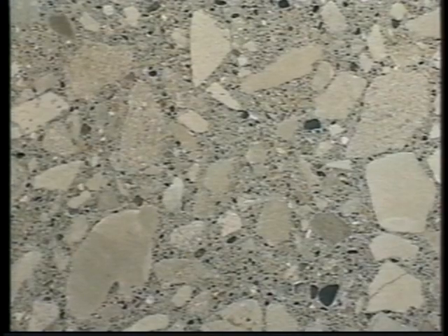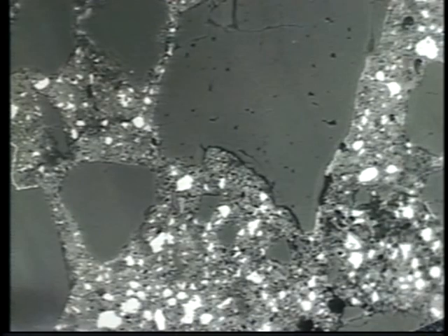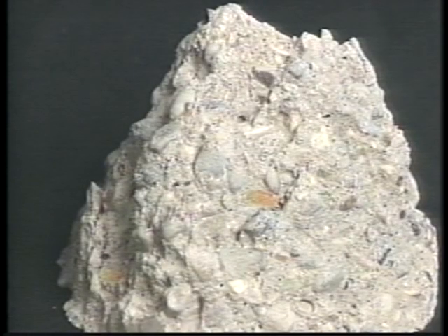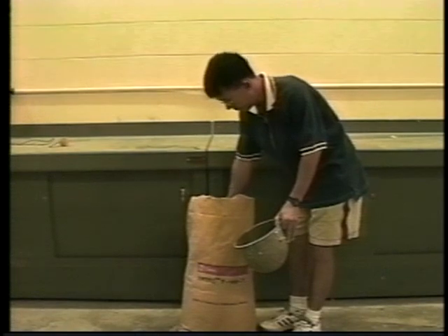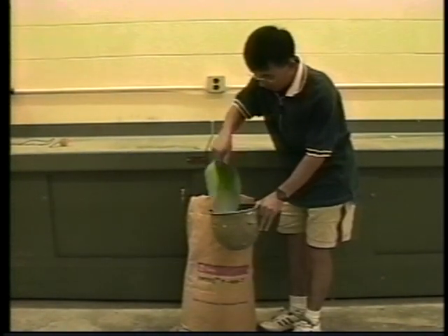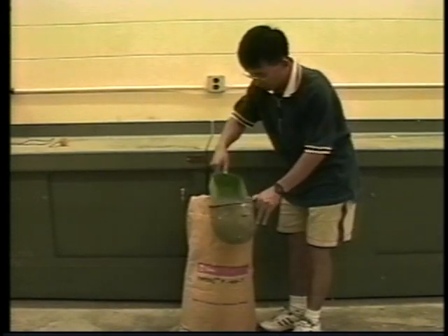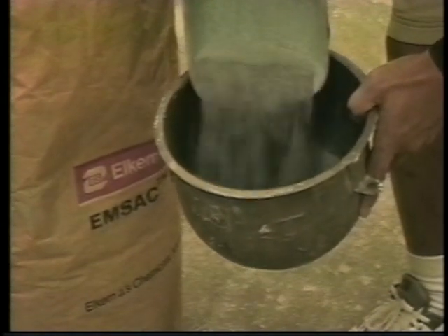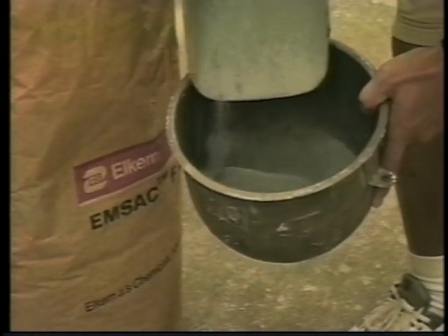The microstructure of concrete helps us understand why processing techniques and admixtures work. In concrete, one of the chief ways to engineer microstructure is to alter the ITZ. For example, if we look at a fracture surface of concrete, we find that the cracks generally run around the aggregates through the ITZ regions because they are weak links in the microstructure. We can densify the ITZ by adding mineral admixtures like silica fume or fly ash to the concrete. The small particle size of silica fume will improve packing and provide silica to densify the ITZ by chemical reaction.